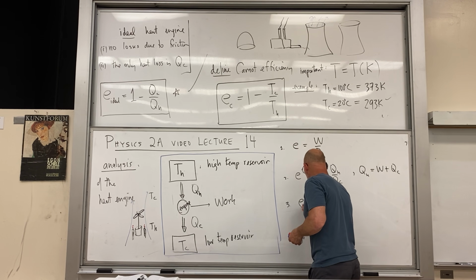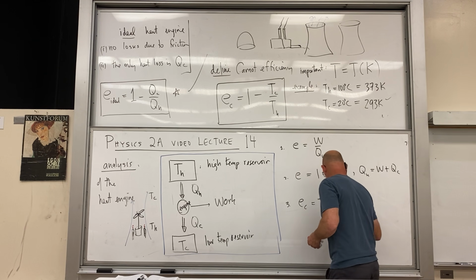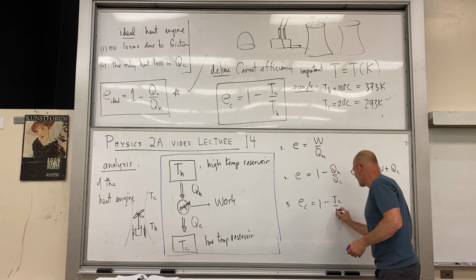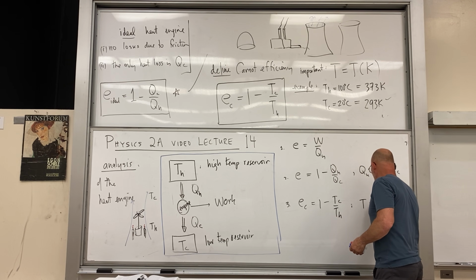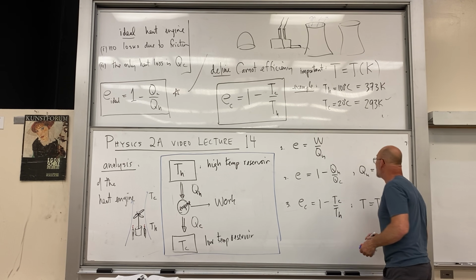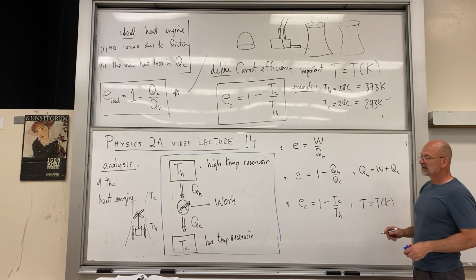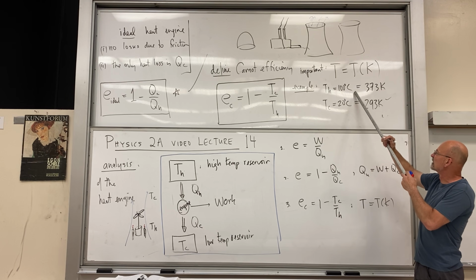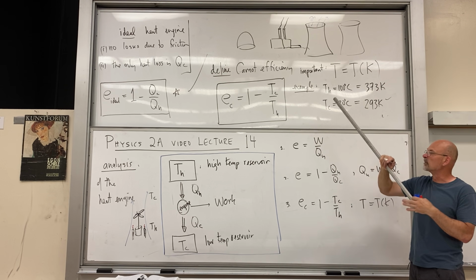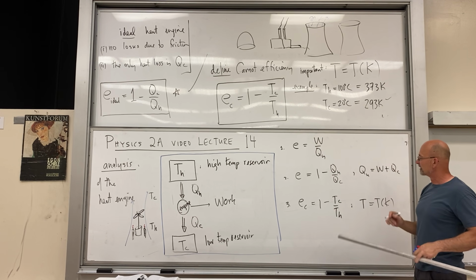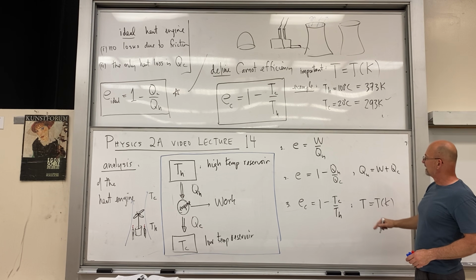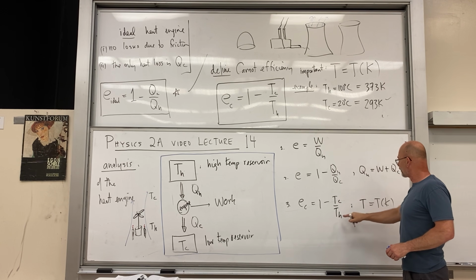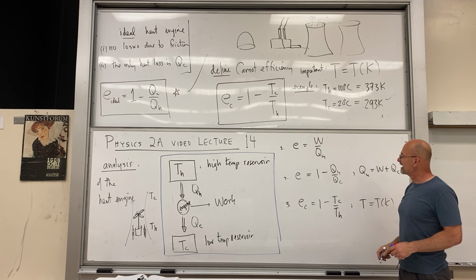And then we have the Carnot efficiency, 1 minus TC divided by TH, where T is in Kelvin. But it's fair for me to state the temperatures in Celsius, because those are common ones. You have to remember to convert them. Okay, anything else? Yeah, these are basically your formulas, 1, 2, 3, 4 for the whole heat engine discussion.